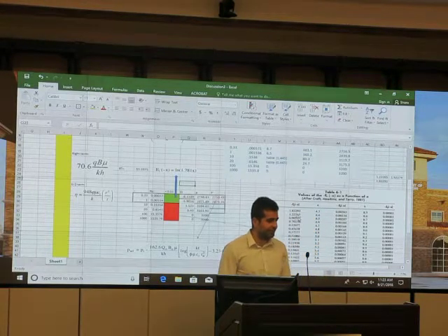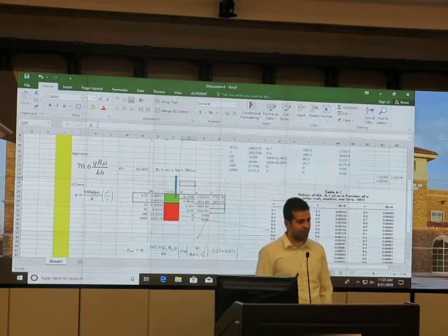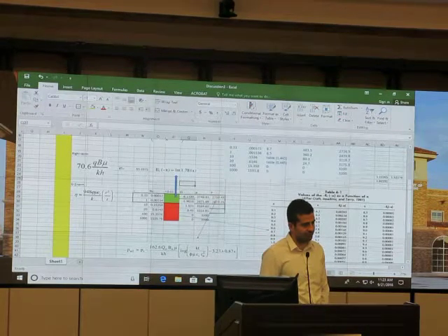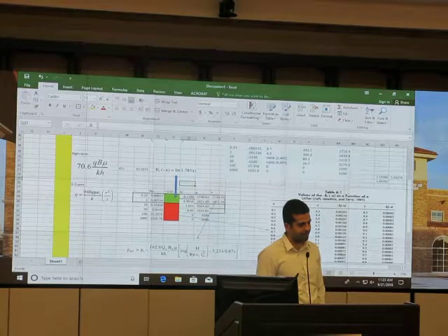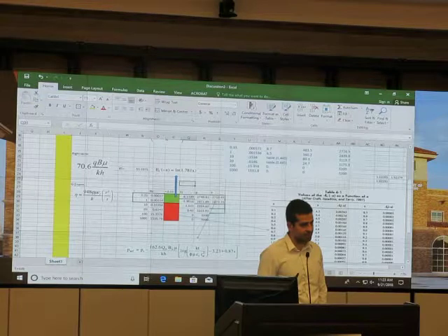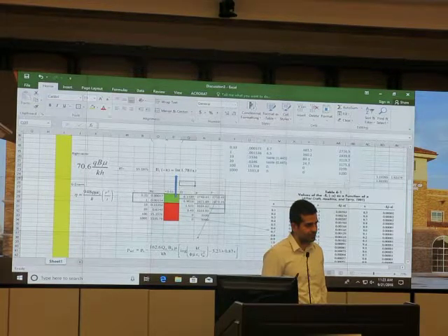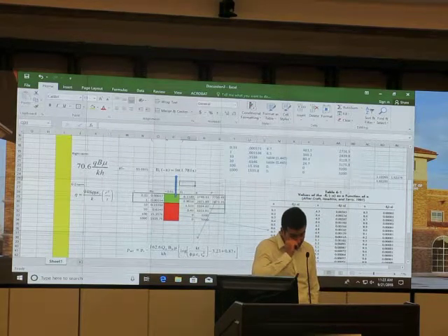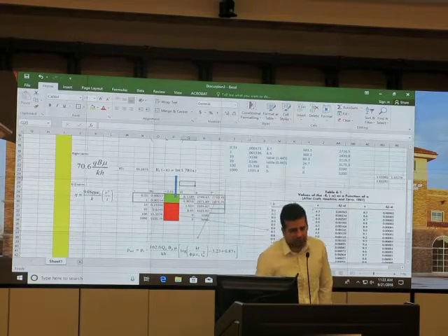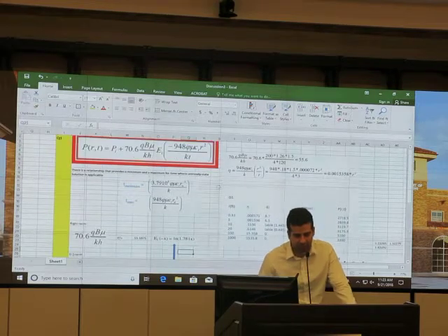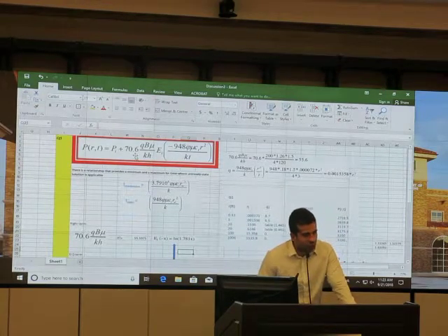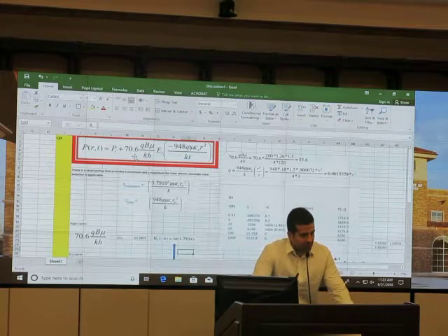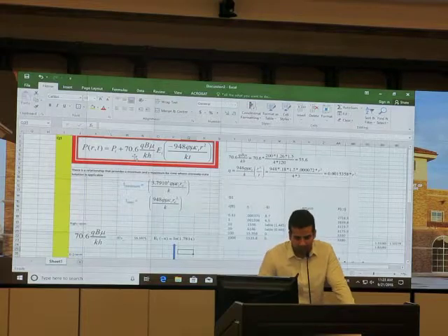If, regardless of what method we use, the numbers are very close, how do we, if we're using the other equation with the skin factor, check if x is less than 0.01? Because there's no x in that equation. Okay, so I'm going to tell you how to calculate that. Remember, in logarithmic format, you have an actual skin factor parameter inside the formula, right?